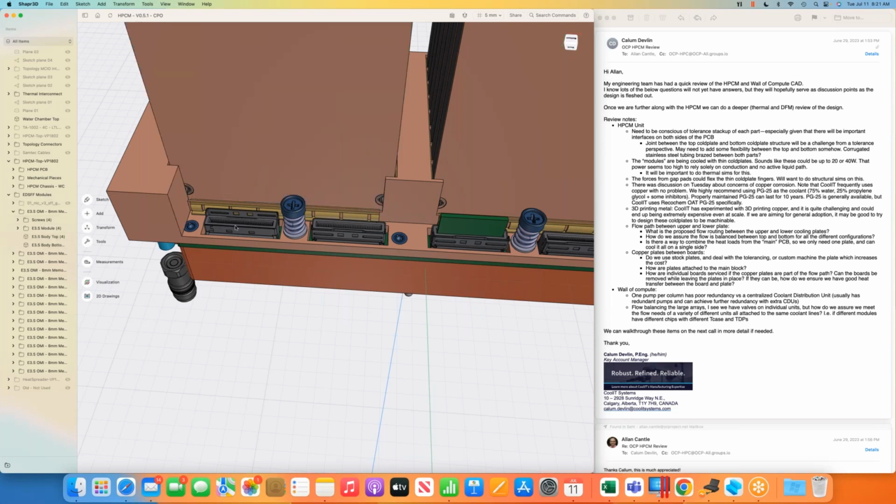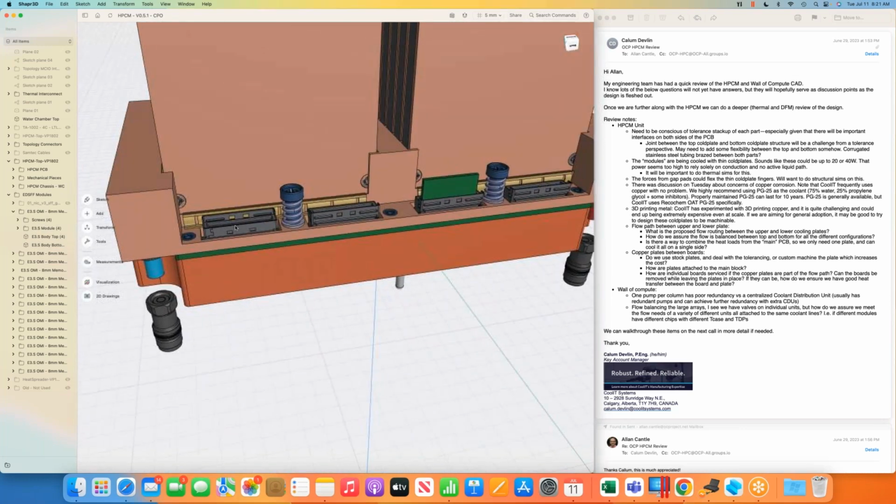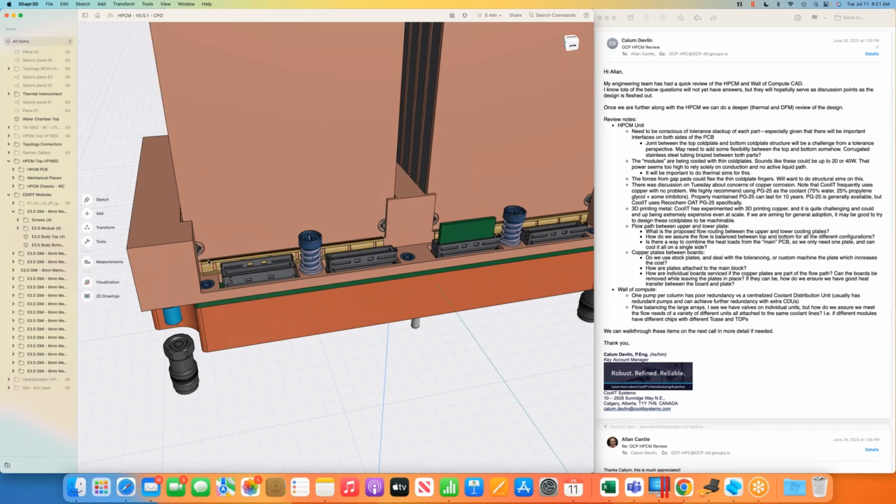Okay, so they are not submerged in the water? No, not immersion type. They're conductively cooled through these. The water's flowing through this copper chamber, so the water is directly underneath the module, and this is the inlet water, so it's relatively cool, and that will be pulling the heat out of the module through the copper plate.